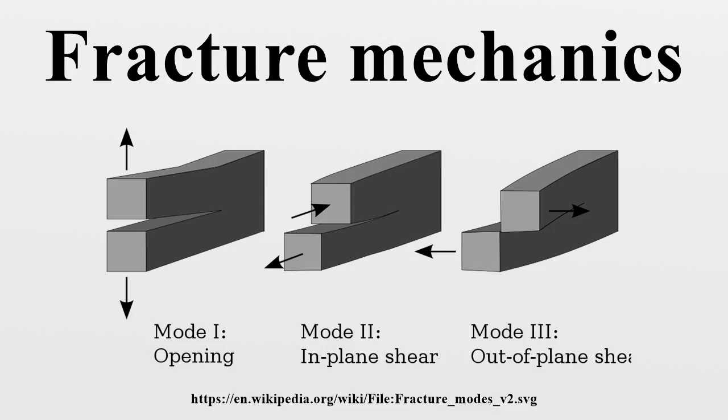Also, experiments on glass fibers that Griffith himself conducted suggested that the fracture stress increases as the fiber diameter decreases. Hence the uniaxial tensile strength, which had been used extensively to predict material failure before Griffith, could not be a specimen-independent material property. Griffith suggested that the low fracture strength observed in experiments, as well as the size dependence of strength, was due to the presence of microscopic flaws in the bulk material.